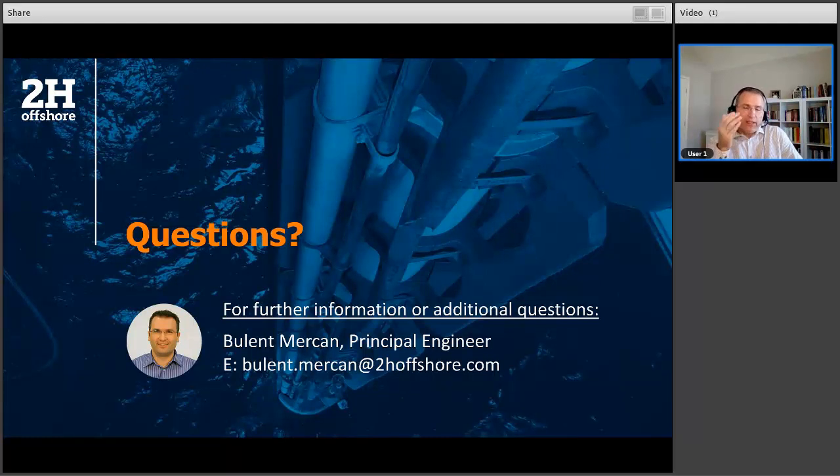Like I said, it's occurring at low frequency, and these accelerometers cannot be used to capture low frequency motion. So you need to have a different set of sensors, or you should use position sensors to measure the riser response. But yes, we did other checks in the study for VIM, but it's not presented here.